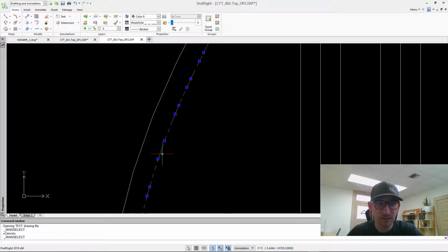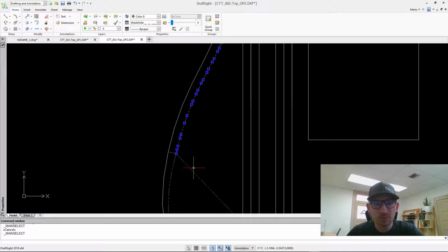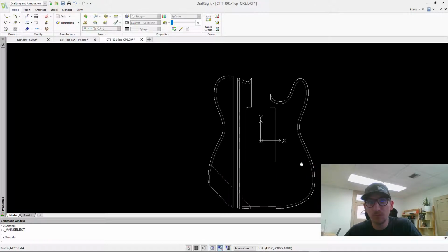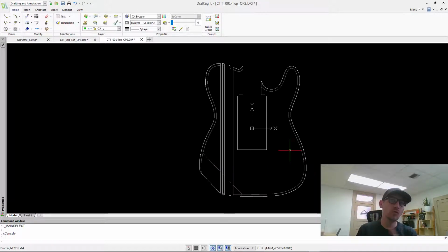It is a polyline. And what's really cool is it sent it out as dashed or construction lines. So I think it's a very useful tool. You can see that there are two ways of exporting a DXF/DWG file from a part file.